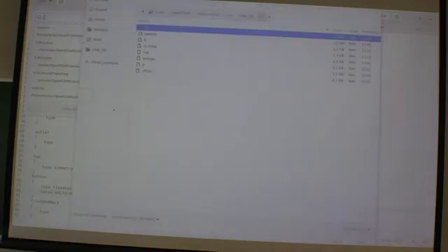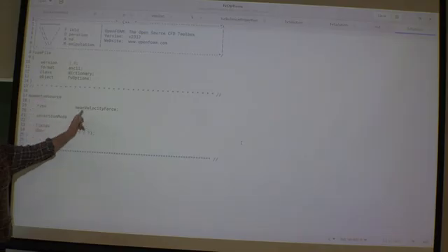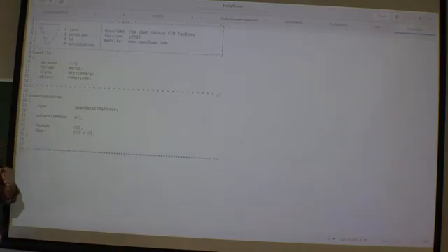Inside my constant folder, I now put a file called fvOptions. fvOptions is a file where you can specify a given source. I want a mean velocity force. I want an external force so that my field U has a value of 10. Okay, why not? 10, that was the same average value as for the Pitts-Daly case, right? So we can use 10, fair enough.